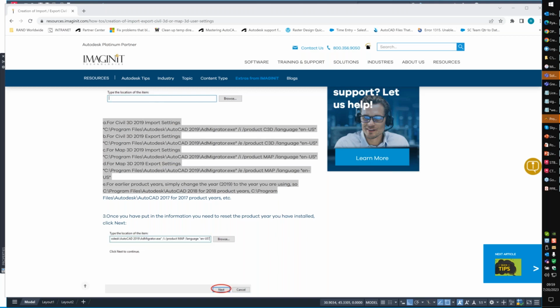Is there a way to set the default elevation to a polyline to 0? If it's picking up adjacent elevations, set OSNAPZ and set that to, I believe it's 1, set that to 0. You have to do that every time you open up the drawing because it's not a saved value or variable. So let's see, OSNAPZ.